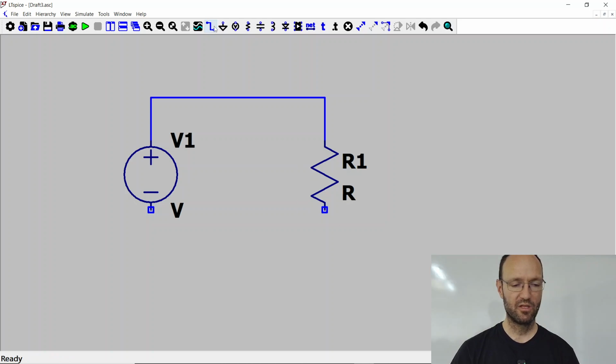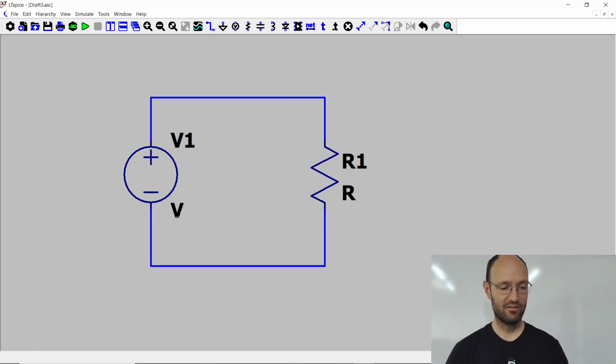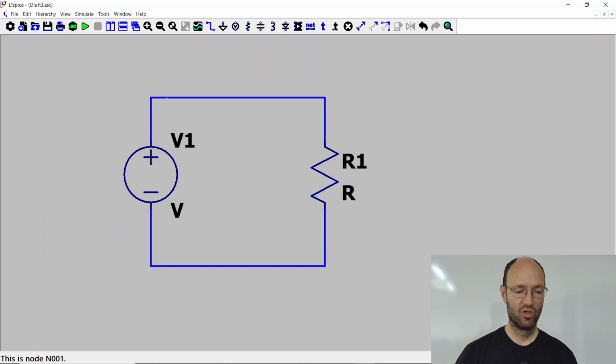because now it's properly connected. And then I need to have a second wire going back because we know current always wants to go in circles. So we have a wire for the forward current, we have a wire for the return current. When you have by accident drawn a wire at the wrong position and want to delete this, then press Delete on the keyboard. Then the mouse will turn into a small scissors symbol, and with the scissors you can then remove or cut wires that you don't like to have in your schematic anymore.